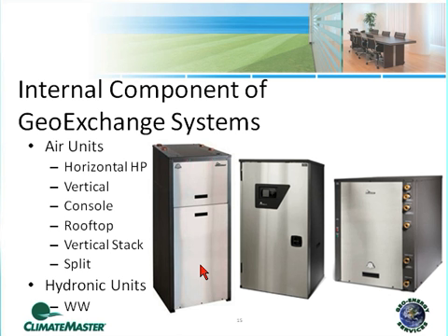with that 120-degree hot water. But assuming that that's not the case, in some small markets where we've got radiant systems or baseboard systems that we want to retrofit, there's this nice little 3-ton water-to-water unit that's capable of making about 140, 145-degree hot water at rated conditions. So it has its unique place. The problem is, though, it's very small in capacity, so it has extremely limited applications, but I've actually used it on 3 projects where that was a great little fit for that situation just because I needed high-temperature hot water, trying to retrofit out an existing baseboard house, and it was a good fit.